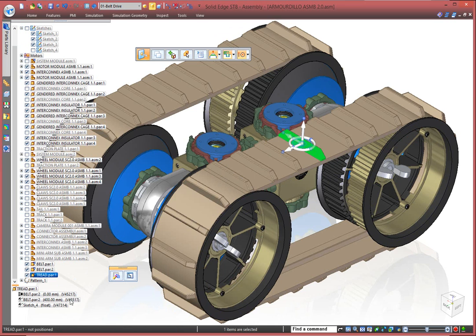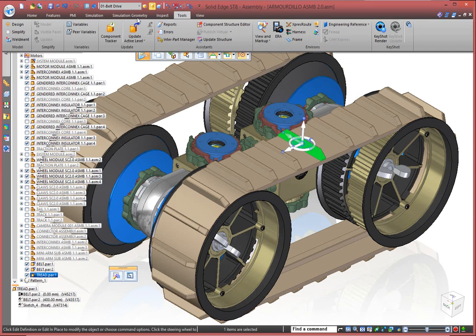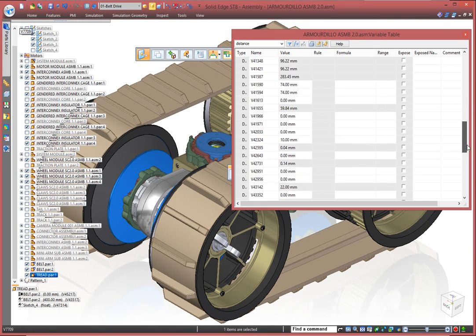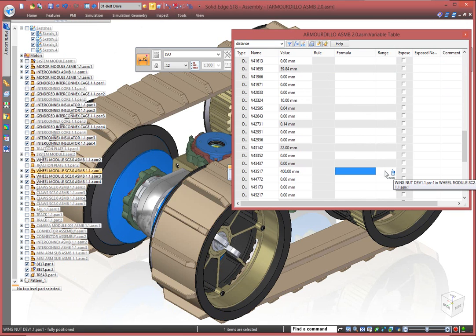We mentioned digital mockup earlier, and the tools we've used so far to help us set this up. Because we want to synchronize the belts with the wheels, we can quickly set their driving variables to be equal. Notice here we will set the tread variable to drive wheels, which sets the value to 300.